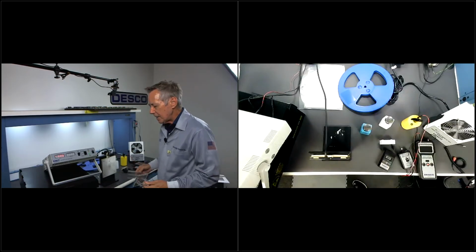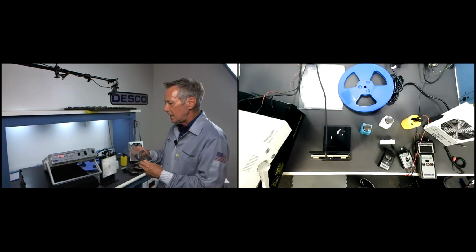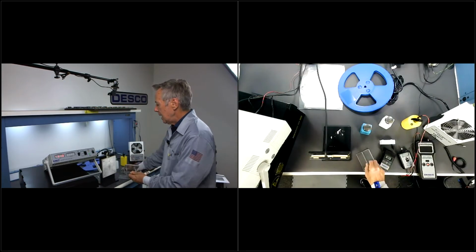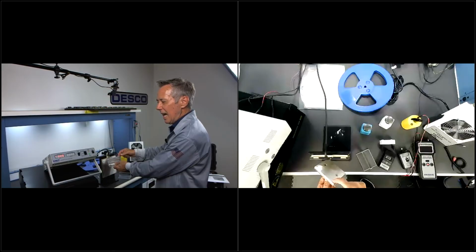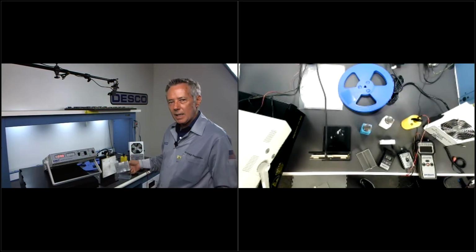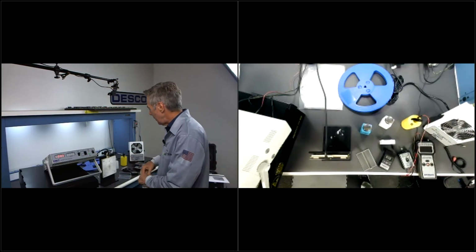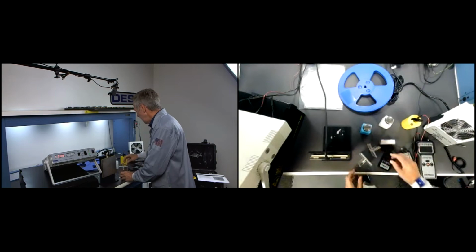I'm going to ground this. I'm going to hold my foot up off the ESD floor here, all right? I'm going to hold this conductor in the presence of the charge plate analyzer. Now I'm going to touch it, and you'll see that charge drop down because I also ground it with my body. So it doesn't matter what the conductor is. It could be me, it could be the mat, could be an ESD safe cart, something like that. When I set that conductor on that surface, it's going to safely ground that charge away.